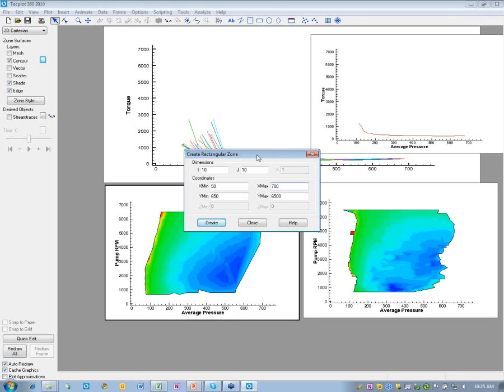There's a lot of cases you can't triangulate that you can interpolate. Now, the other thing that comes up with some frequency is the difference between doing a linear interpolation, say, and doing kriging. Where are the areas where using kriging might be more effective?